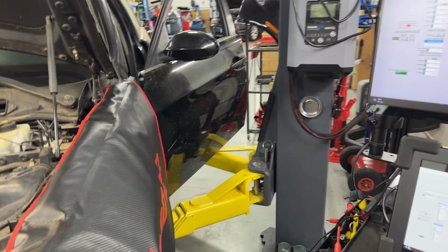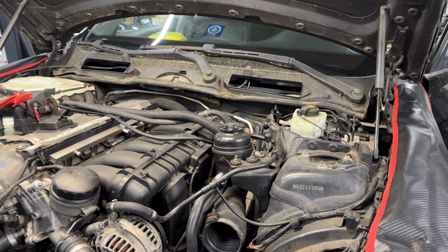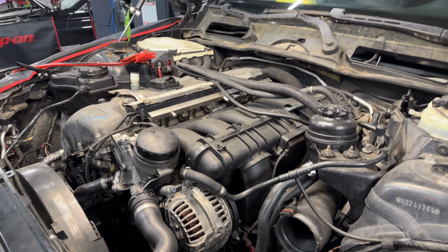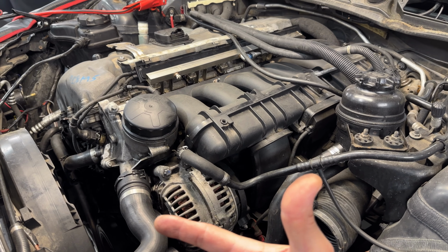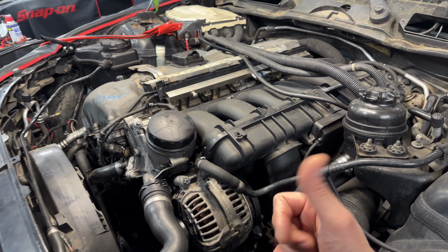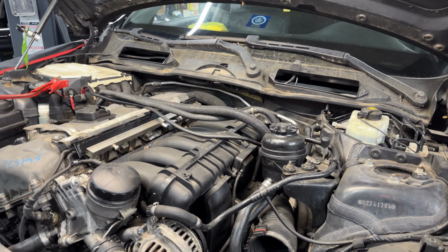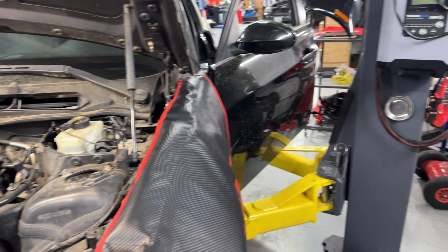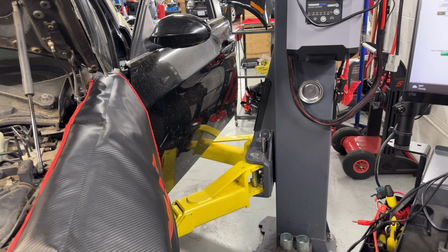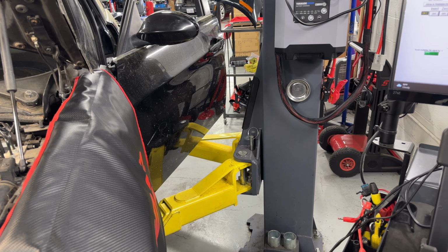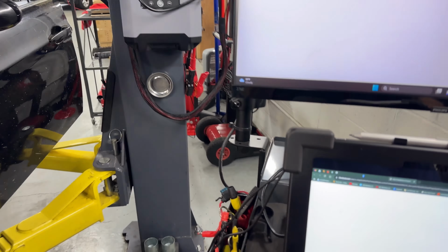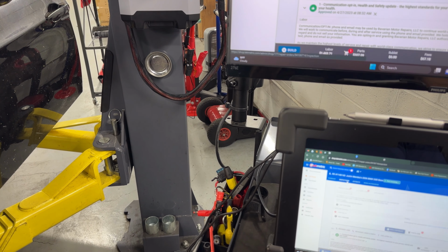All right, going back into the vehicle, the customer concern is a BSD network down, so it had overheating. The fan came out at maximum speed, and then it was, what's the name? Electrical pump disconnected. Let me show you the fault. Just make sure that I'm not showing you the customer information. So I'm going to go down a little bit just so I show you the information.